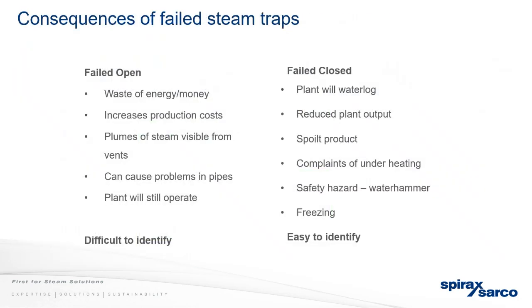So, consequences of failed steam traps. If they fail open, it's a waste of energy, so you're wasting money because you're losing steam. It increases production costs, because with those leakages, running your process is going to be more expensive. Plumes of steam become visible. Those of us in the steam industry quite often have the public around our buildings see steam and think it's smoke, so that normally ends up with a lot of complaints. If you can see the steam venting, you are still losing money. It can also cause problems in pipes, with more erosion and corrosion, but the plant will still operate.